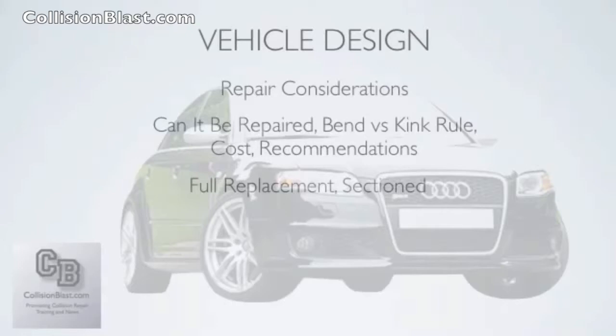But a lot of times you can get by with sectioning. For example, on a quarter panel, rather than going all the way up to the factory seam, you can section it in a smaller area, like up by your back glass, without getting into the roof panel. So those are some different repair considerations. And again, until we get deeper into it, this is kind of an overview, just some things to think about and consider.